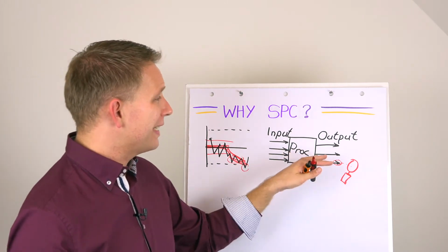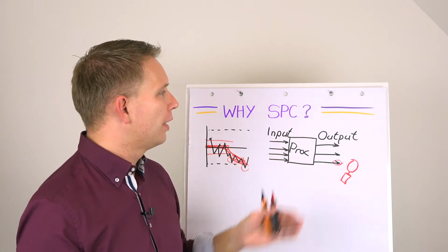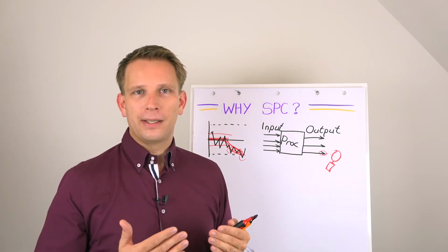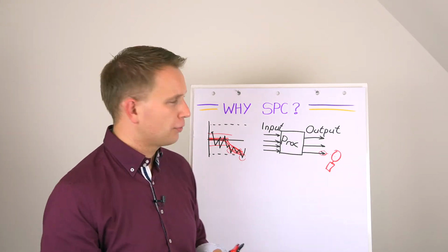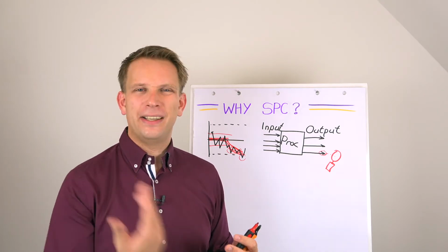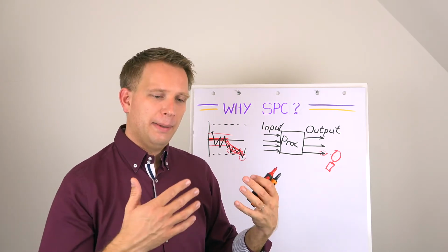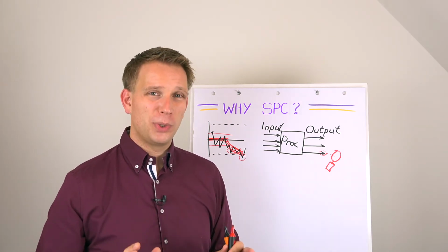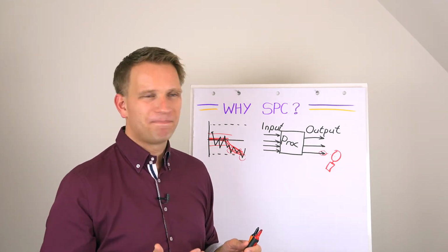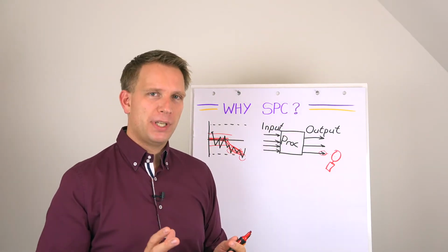Things like that, so quality parameters, weight parameters, production parameters are very good to do statistical process control on. What is not really a good thing to put statistical process control as an output is the amount of production, and then specifically in, let's say, a line speed. So we have OEE, overall equipment effectiveness, measurements for that, and they are much more suited to that task. Statistical process control on, is my machine running well? It will not tell you a lot. This is about the stability of the process itself.